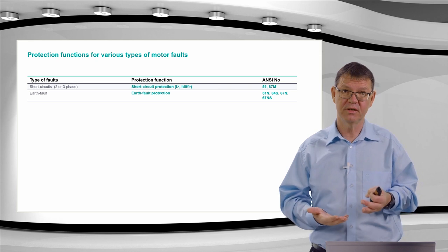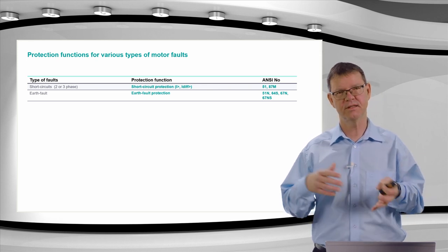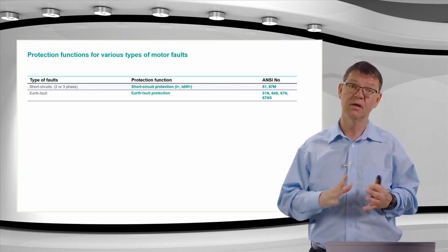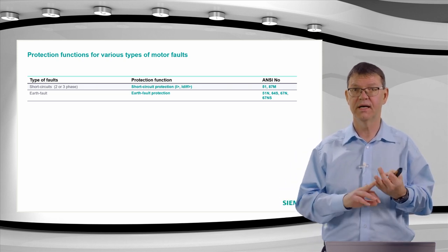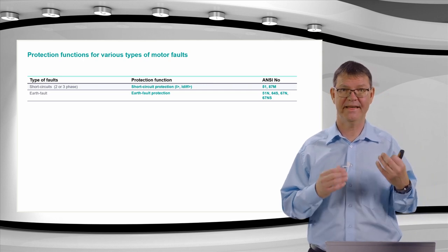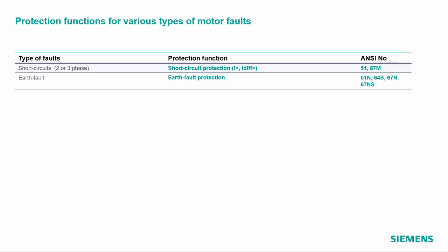And we must differentiate here between grounded networks and basically isolated or compensated networks. For the grounded networks, the standard overcurrent function will do. For the isolated and compensated networks, we have dedicated special protection functions for that situation. And they are very similar or identical, I would say, to what we encounter in medium voltage grids in the distribution area. Here in Central Europe, we very often have these Peterson coil grounded networks, and also there we use dedicated sensitive directional ground fault protection.